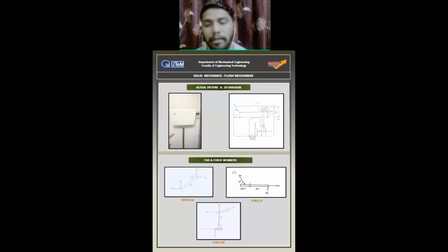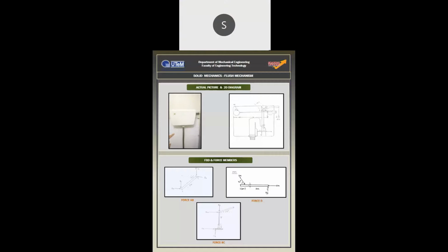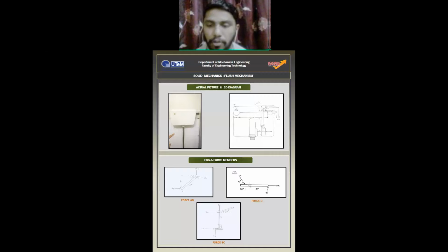After that, the tank empties quite quickly and the float ball floats to the bottom. That means the float rod is no longer pressing against the valve, so water begins to flow into the tank, filling it up again. Lastly, the water which left the tank goes through a short pipe to the toilet bowl. It swirls around the rim, down the side of the bowl and out through the drain pipe.